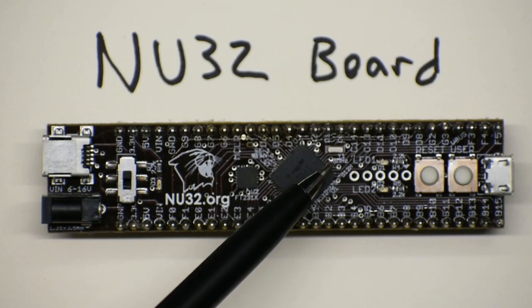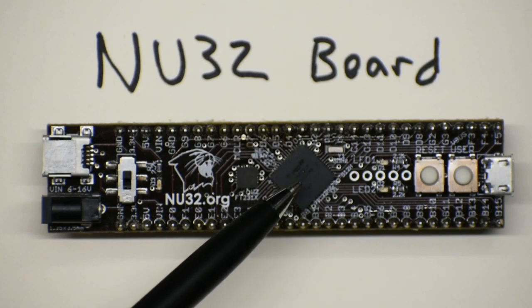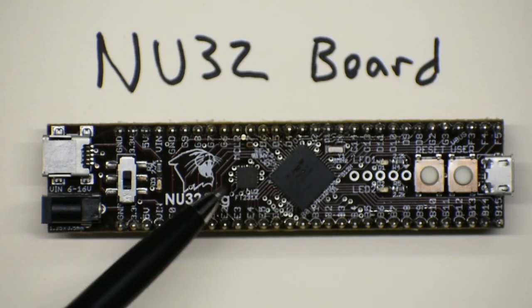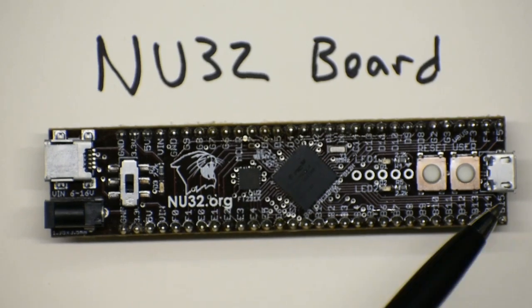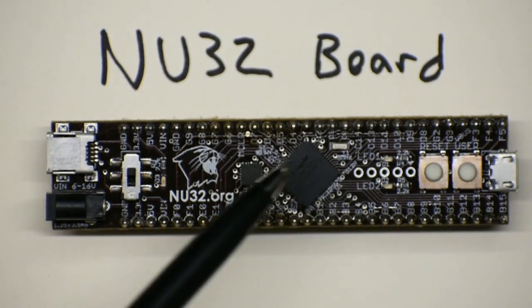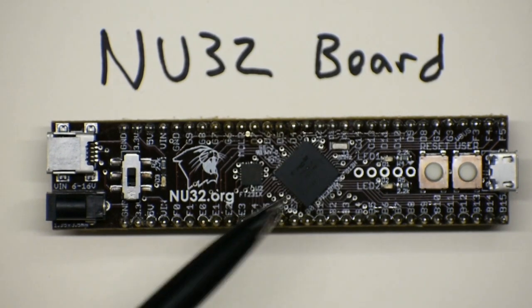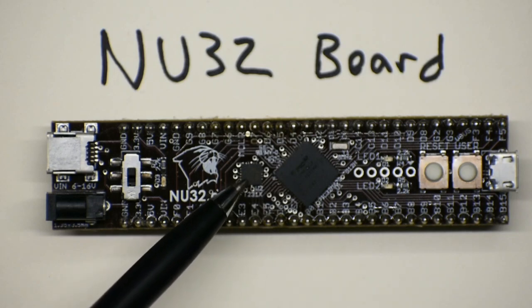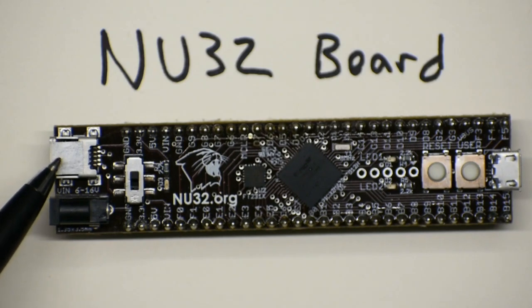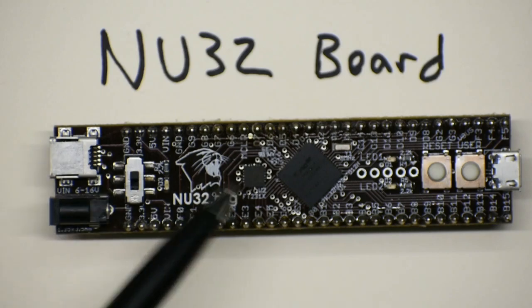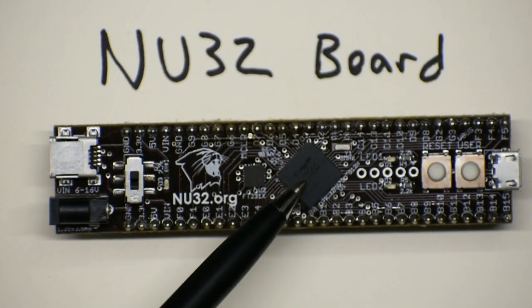There's a little silver chip next to the PIC. That's the crystal resonator that goes at 8 megahertz. So that goes as an input to the PIC, and the PIC turns that into 80 megahertz. There's another little black chip next to the PIC. So the PIC is capable of talking USB to this micro USB connector on the end of the board. But rather than use the USB module to talk to your computer, the PIC talks what we call UART, or serial communication, to this FTDI USB to serial converter, and this chip talks to the mini USB port, which is what we primarily use to program and debug the PIC.